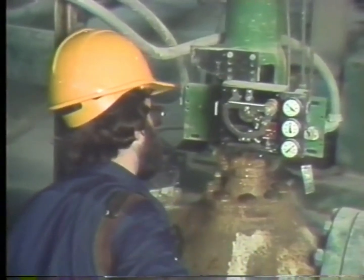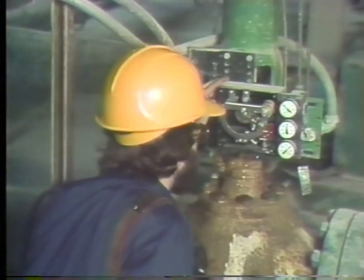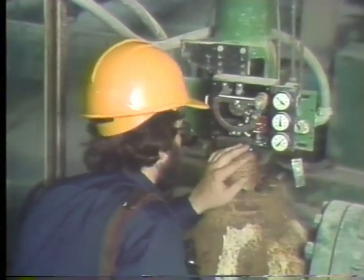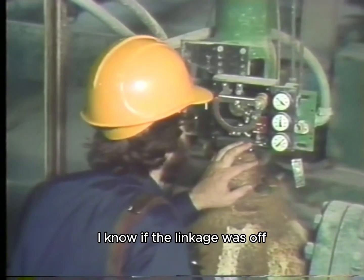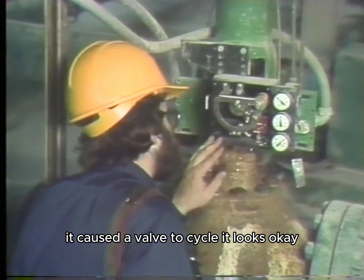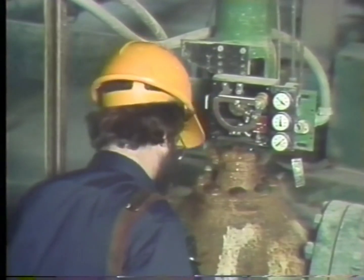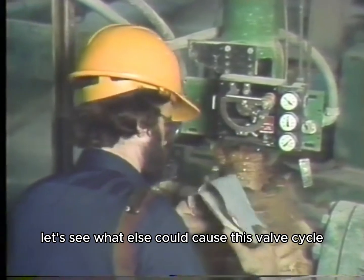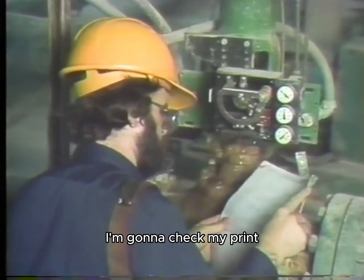Let's see. Everything looks all right. Nothing loose. I know if the linkage was off, it'd cause the valve to cycle. It looks okay. Let's see. What else could cause this valve to cycle? I better check my print.